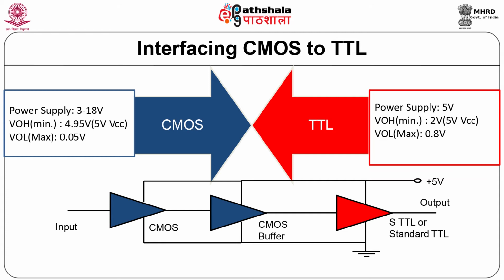As a rule of thumb, a CMOS IC belonging to the 4000B family, which is the most widely used CMOS family, can feed one LS-TTL or two low power TTL unit loads.